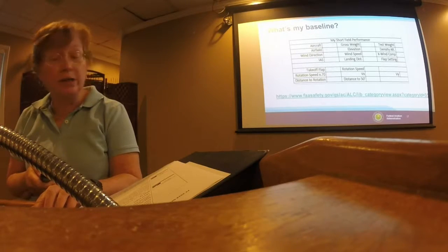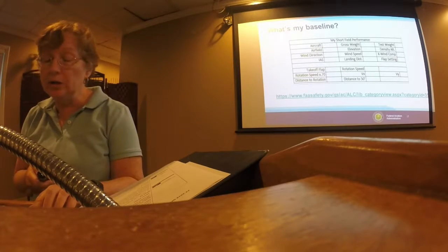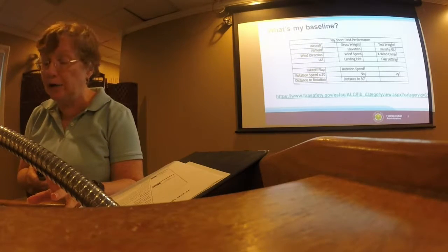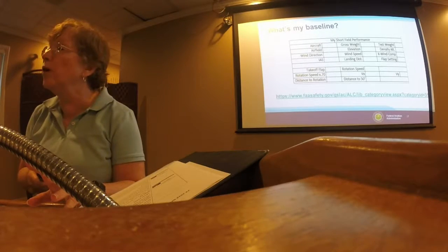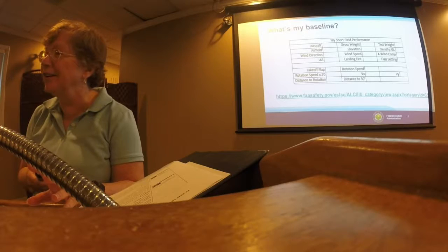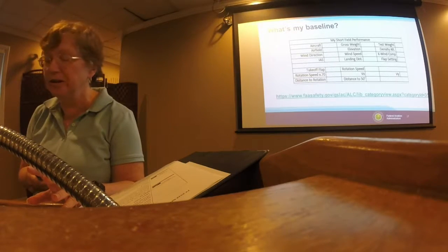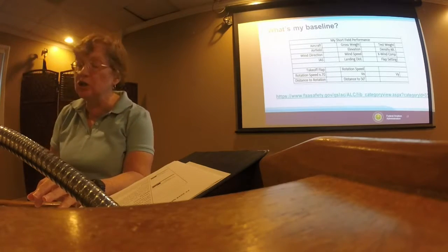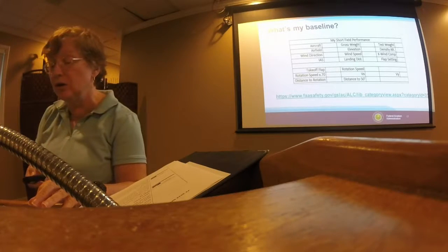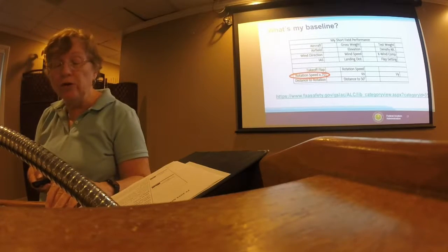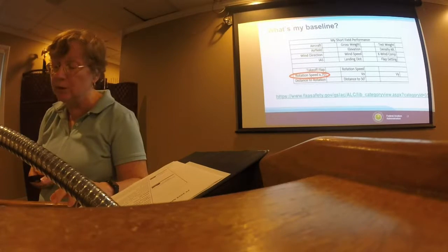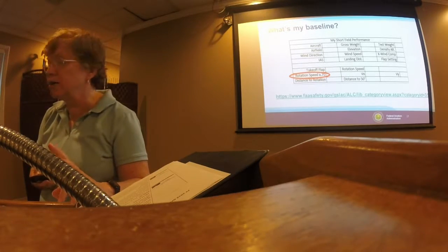So to establish your baseline, you need to load your aircraft with a typical mix of fuel, cargo, and passengers. Probably a good idea if one of them is a CFI, maybe to stop you from doing something weird. Calculate your test weight and note the runway condition, elevation, the density altitude, wind direction, and speed. Also note what rotation and climb speeds you intend to use and calculate 70% of the rotation speed. We'll talk about that in a couple slides.